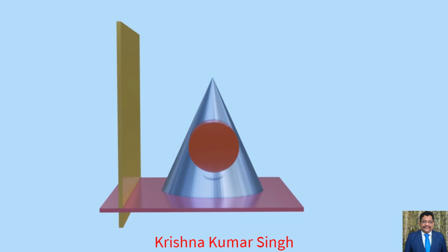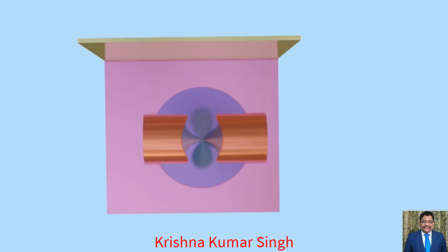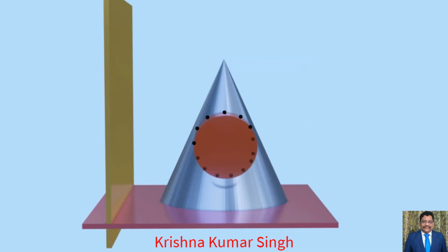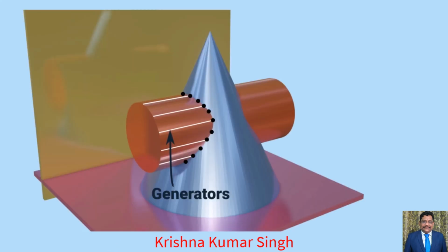Step 4. Now draw all the views of the penetrating solid, beginning with the side view, then top and front view of the penetrating solid. Step 5. Now on the side view of both the solids, mark the points and give them lettering. Step 6. For marking points, follow this rule: the points which are on standard edges, standard generators and on the edge of the solid standing on HP, mark those points on their respective front view and top view. The remaining points should be located on the top view first, and then on the front view.